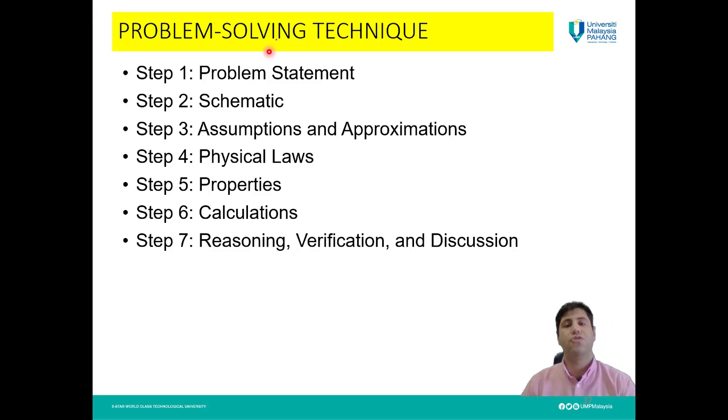Okay, now I have introduced you to some basics, some units which you require for your calculations to solve different problems related to thermodynamics. Now I'm going to tell you how to solve problems, which we call the problem solving technique. Step one is the problem statement. You should be able to state a problem, to say what is known, what is unknown, what we are going to find. Step two is to draw a schematic.